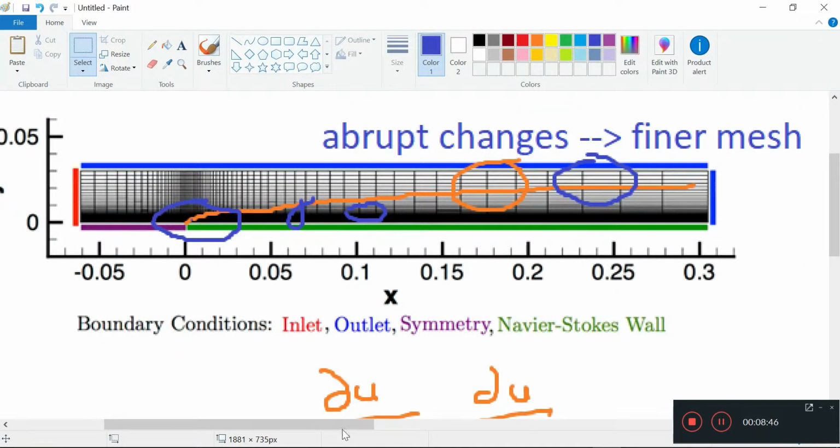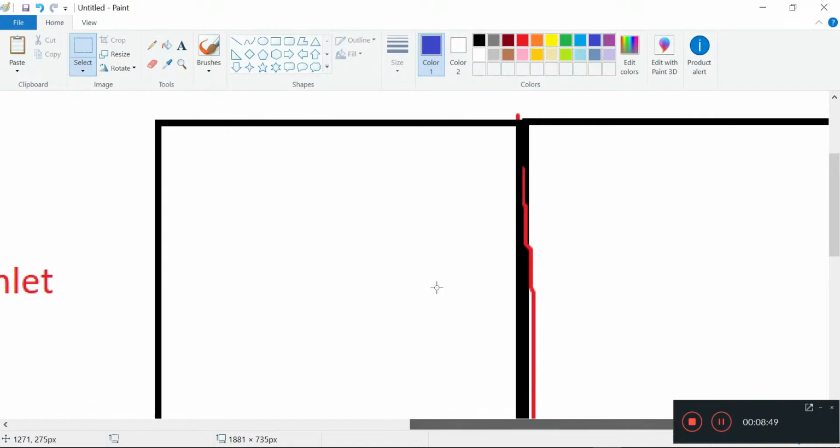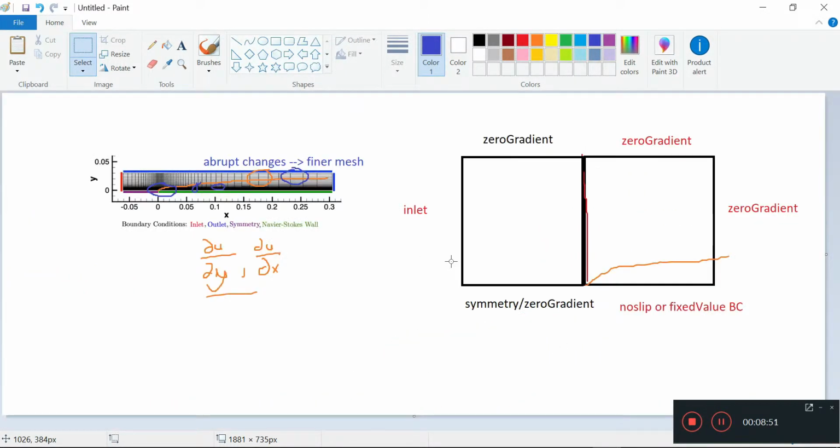Okay, so how are we going to change our geometry file like so? We first extend this boundary here, duplicate whatever we have on this right hand side and duplicate it here, and after that, of course, we have a mesh like so. In these blue areas, we want it more refined, just like what we see here. How are we going to do that?